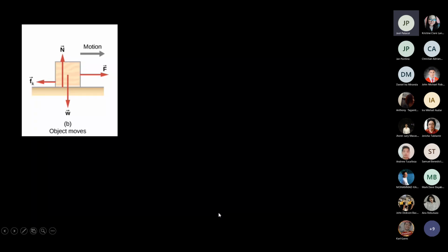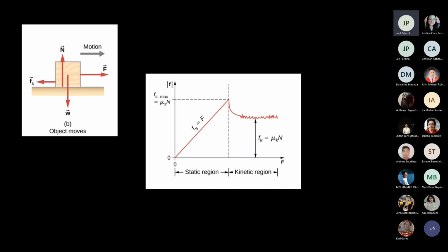As soon as sliding starts, the frictional force usually decreases as it is easier to keep the box moving than to start moving it. Since the box is already sliding, the frictional force in operation is the kinetic frictional force. This diagram illustrates how the static frictional force is building up during the period that the box or the block remains at rest.